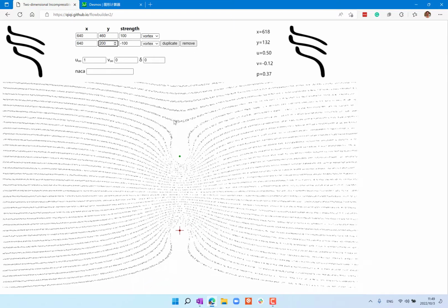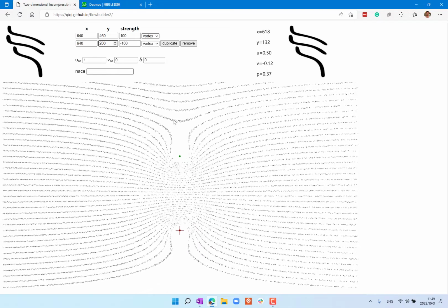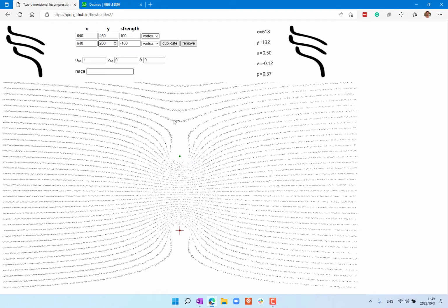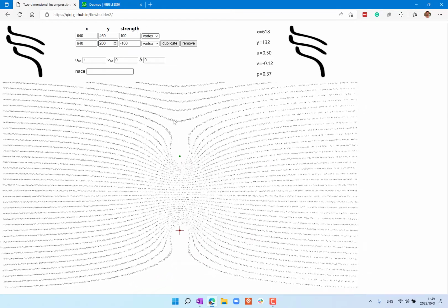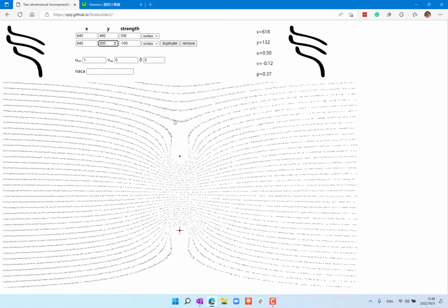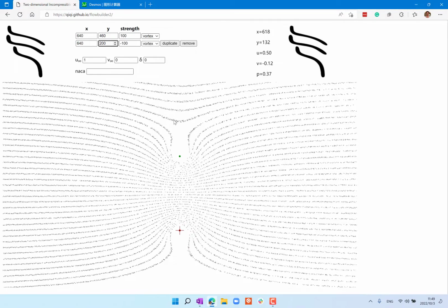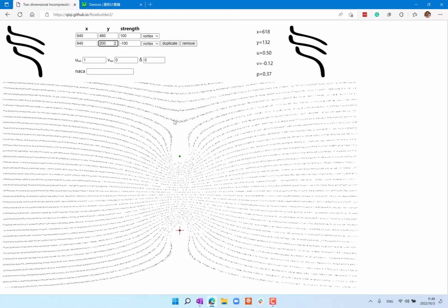So that means the velocity is higher over here. Higher velocity means narrower stream tubes. And narrower stream tubes on the two sides means the particle starting at quarter height is going to be closer to the center or the boundary? Boundary, right? Because at the boundary, the stream tubes are narrower due to higher velocity.